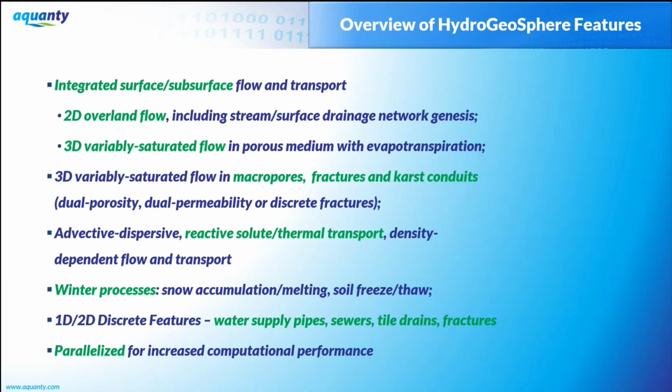You can start the model out with no surface water at all, no lakes, no rivers flowing, and a water table at arbitrary depth, and you can begin raining on it or applying precipitation during a spin-up process. And if you get things right, the geometry, the hydrology, the hydraulic properties, the DEM, it will actually form the drainage network. In other words, the rivers and streams, the wetlands, the lakes, etc., which is really interesting to watch evolve.